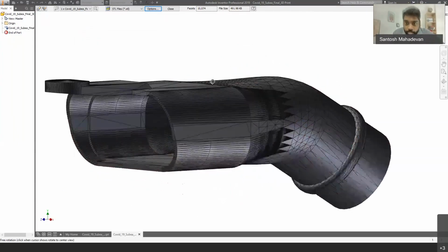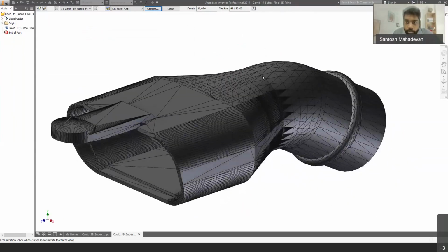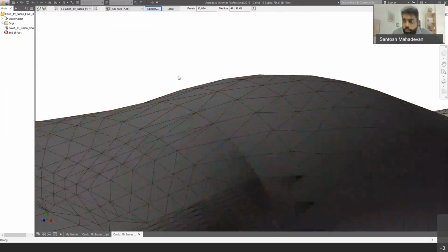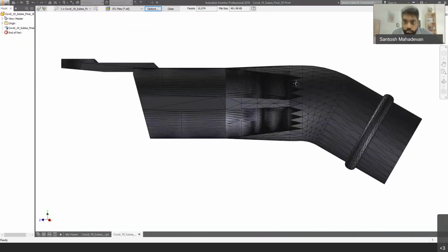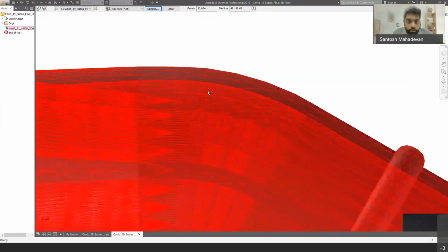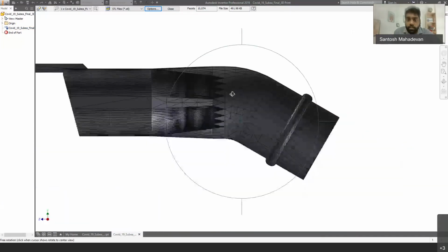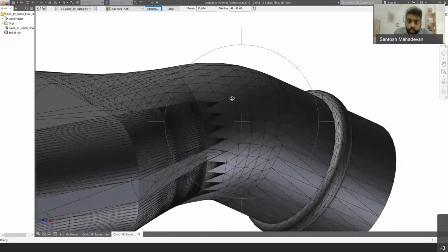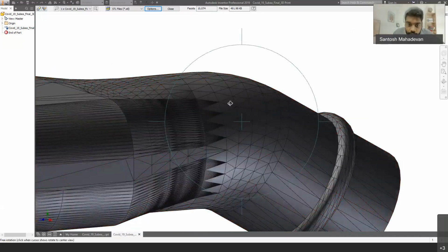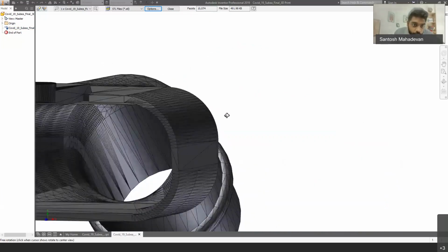So as you can see, the same part has formed a very weird geometry on this radius. If you can see that, you have a line here and then a line there and then another line. You have about 1, 2, 3, 4, 5 simple lines that are used to create something that looks like a curve. So when I 3D print this part, I will again have these kind of ridges, and those ridges even get multiplied inside.